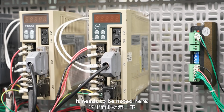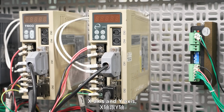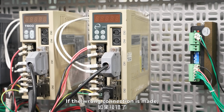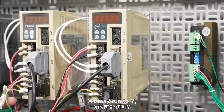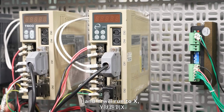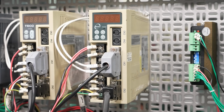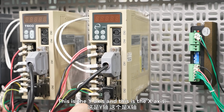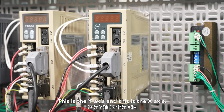It needs to be noted here, because we have two motors, X-axis and Y-axis, so this wire must not be connected incorrectly. If the wrong connection is made, X's may run to Y and Y will run to X, and these errors will occur. This is something that everyone should pay attention to. This is the Y-axis and this is the X-axis.